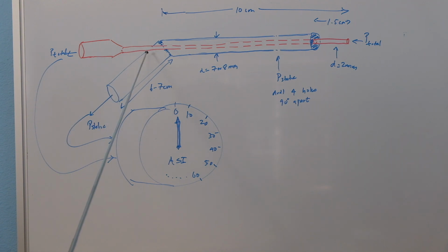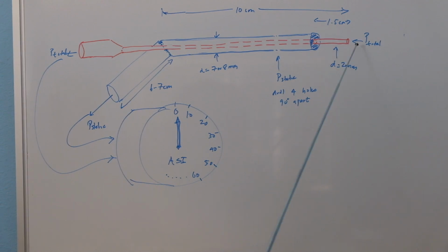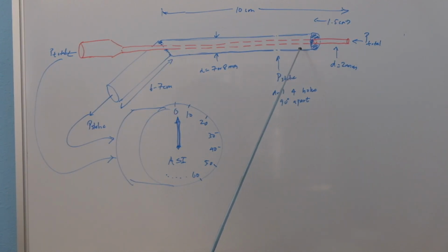Then I drilled a hole on this side over here carefully, and then I threaded or pushed this 2 millimeter tube all the way across to the end. Then I inserted some small wire, like a copper wick, which is wrapped around here and then soldered to block and to center this inner tube into this bigger tube. If you don't do that, this thing will rattle around or it might not seal properly.